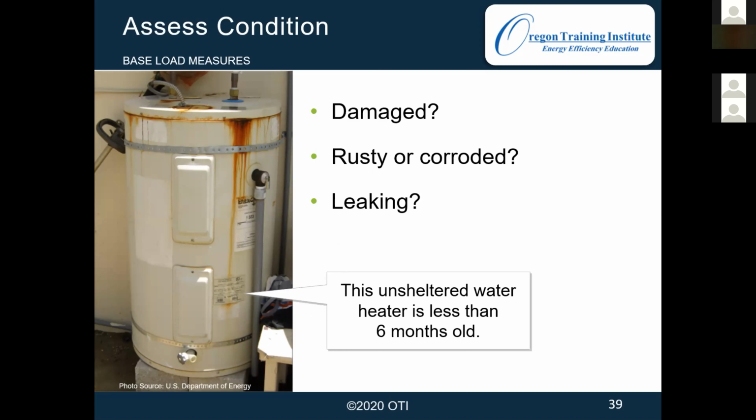If it's in one of the earthquake zones, like, I want to say that east of the Oregon Cascades is in a higher earthquake zone than west, but it also can vary by city and county code. If it's in the garage, it's going to have to be up off the ground, if it's combustion, just in case there's any sort of gas fumes or any sort of fumes in the garage, that's not going to ignite them.